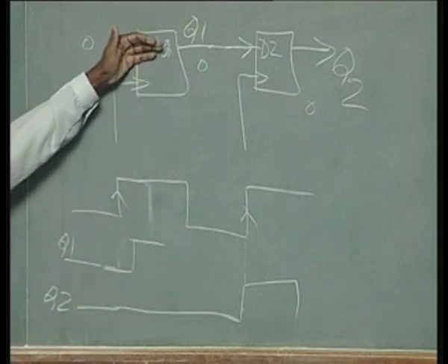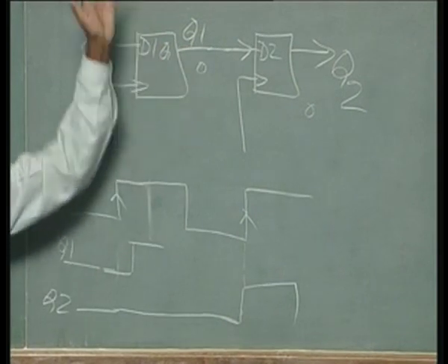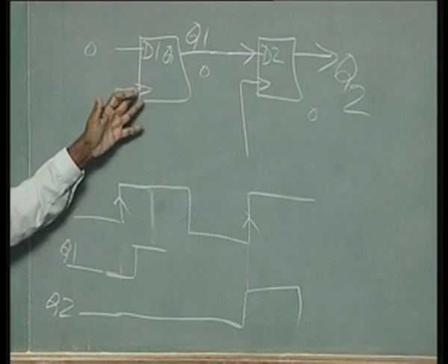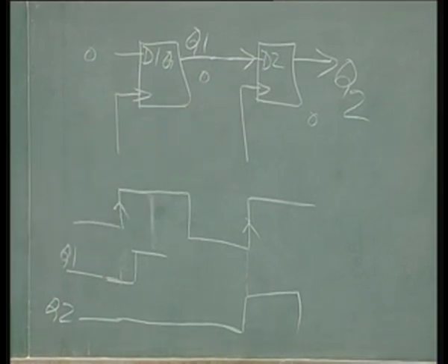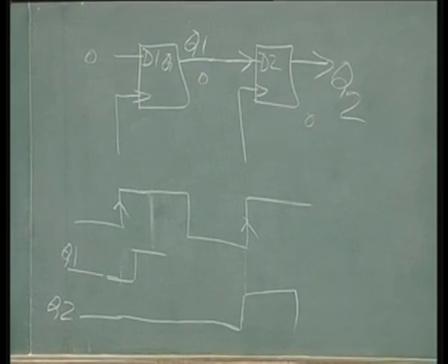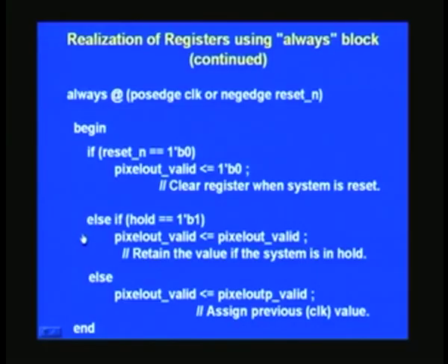So whatever is the first flip flop, that only is being fed here, and that will take effect only with the arrival of the next clock pulse, right? Although it is all a synchronous circuit, you have to have the system clock running all through, and we will see more when we see RTL coding. Okay, coming back to this, the completed waveforms for the D flip flops cascaded is shown. I think the program is clear, self-explanatory right now, and before we go on to the next example, we will just see what these statements are.